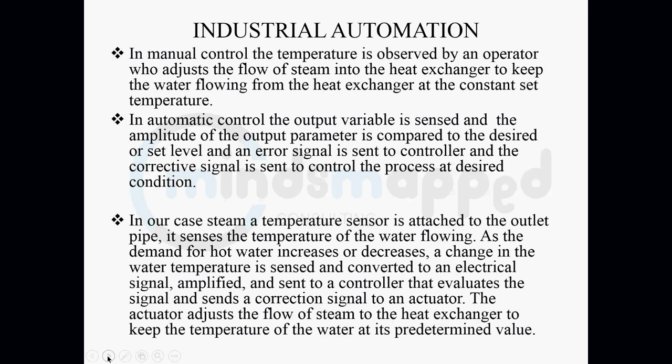It takes this as an error signal and then takes corrective action: if the temperature is lower than what we want, it will open the steam inlet, and if it is more, it will close the steam inlet, increasing or decreasing the heat exchange capability of our heat exchanger and thus maintaining the temperature of the water.